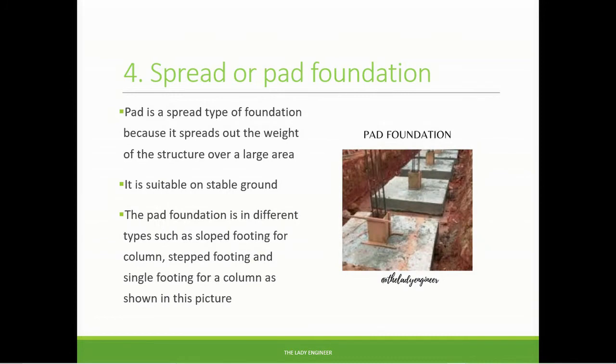Then we have the spread or pad foundation, which is also one of the most common shallow foundations used, especially in multi-story buildings. The pad foundation is a spread type of foundation because it spreads out the weight of the structure over a large area. As you can see, we have a not so big column sitting on a very large base. It is suitable on stable ground. I mentioned most shallow foundations are suitable for stable ground.